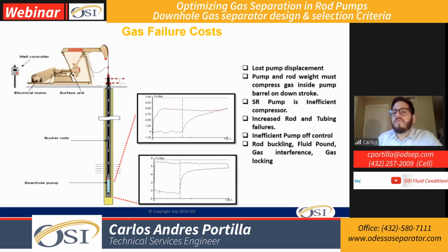As we mentioned before, there are many disadvantages of having gas in the rod pumps, including rod buckling, fluid pound, gas interference, gas locking, and many tubing and rod failures that have you pulling your well, having delayed production, and so on and so on.